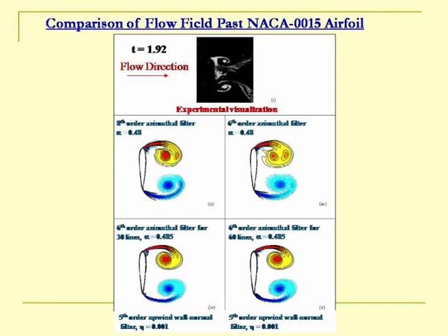It's very difficult to visualize this type of flows. So, the aerofoil is somewhere there, and this is the vortex that is shed from top, and this is another vortex that is shed from bottom. So, there is some kind of asymmetry of the shed vortices because of the asymmetry of the geometry itself. The top side is rounded, whereas the bottom side has got a very sharp edge, and the sharp edge actually brings about a much more diffused larger vortex, whereas the top surface has additional secondary separation occurring from on the surface itself, where this is very well defined.